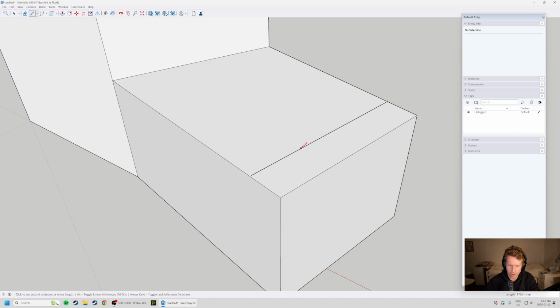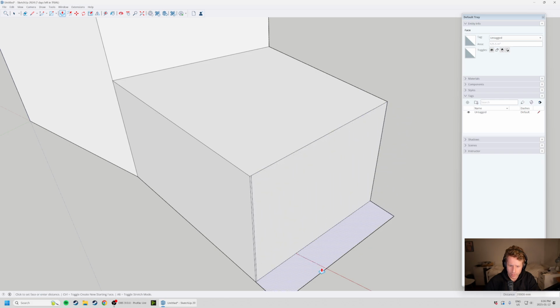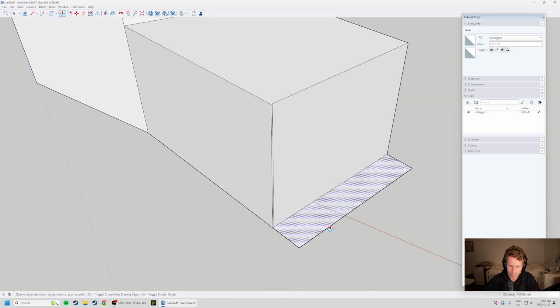We've got a bold line now. And if we drag it across and click once, you can see it's become skinny. And what that means is if I hit spacebar, we've got 2 faces here, which is what we want. So I'm going to go ahead and delete this one real quick and come back to our push-pull. Let's grab this, click once, and we can drag it all the way down. It should disappear.